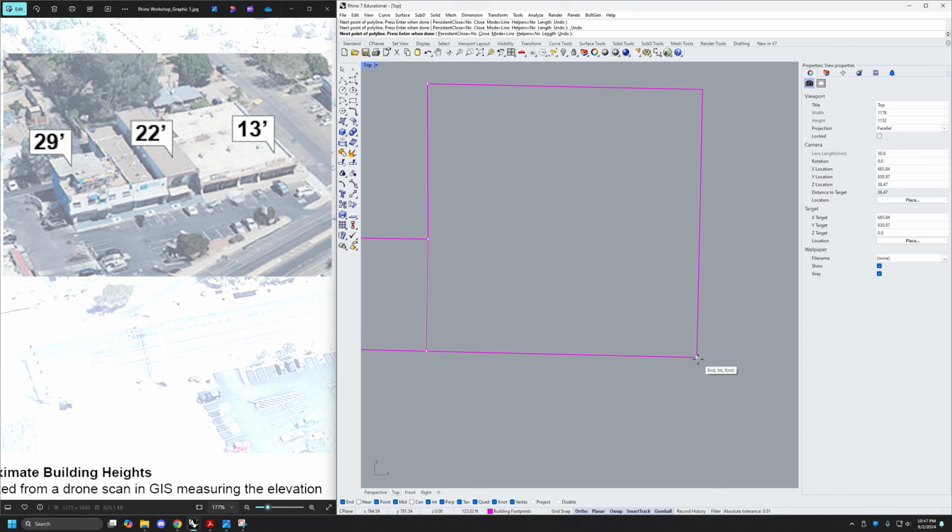Now I'm just going to snap here, press my tab constraints. There we got it locked on that angle. Now I'm going to type in 30. Oh, sorry, it was 40. I think we determined 40 feet. Goodness gracious. Okay, this is really throwing me for a loop. Okay, we're going to type tab, 40. Okay, there we go. You see, sometimes Smart Tracks is too smart.